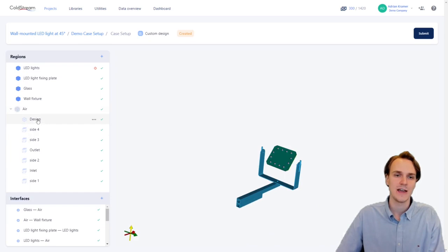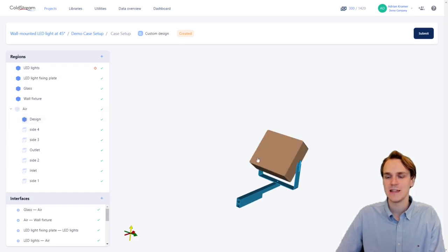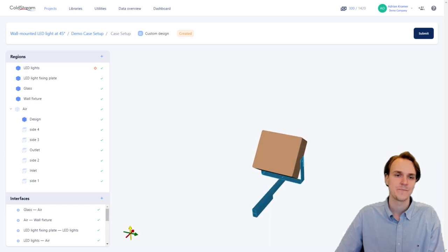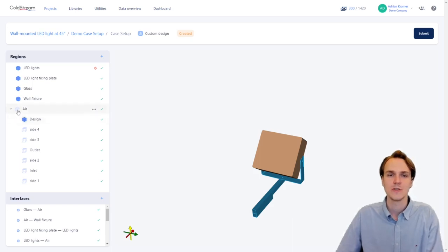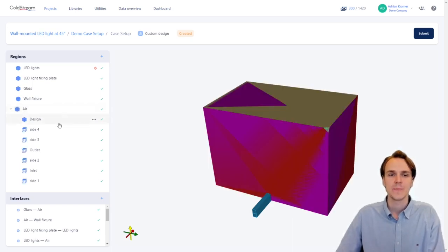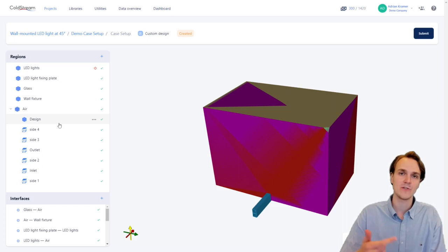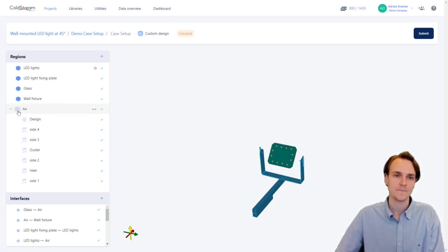We need to define where is the design space that is allowable for the topology optimization. But just with some slight tweaks in CAD, you can have access to thermal topology optimization with just a few clicks. The steps to set up a full case go as follows: solids and fluids, boundary conditions, design space, and targets. So I'll run you through those.